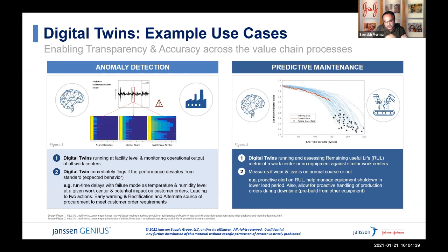Now, we created this golden batch as a reference, as a benchmark, and started comparing it with new batches. In one scenario, I know that we started to see a blip in the feed rate of a feeder of a particular raw material. It was, I think, media. And we were able to immediately stop that batch.